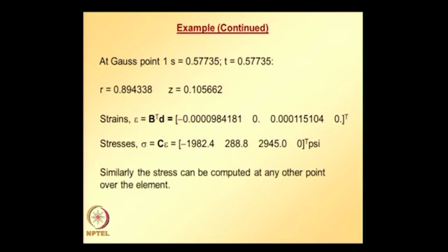Similar stress calculations can be made at other integration points or at any point where it is required. So, basically as a part of axisymmetric elasticity problems we looked at the governing equations for axisymmetric problems, and also the derivation of the element stiffness matrix and equivalent nodal load vector for the linear triangular element and also the 4 node quadrilateral element.